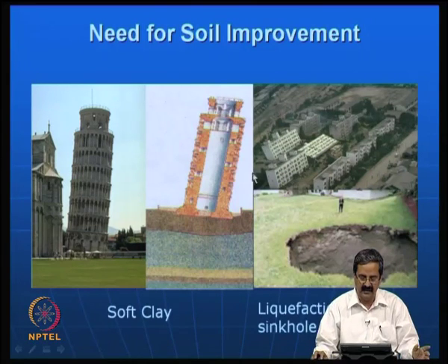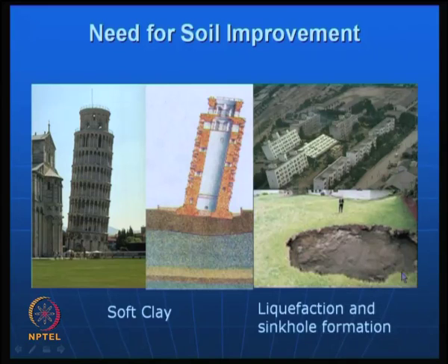This particular case is a liquefaction phenomenon, in which the effective stress becomes zero when the earthquake occurs in the foundation soil. So the foundations just sink in, and you have tilting and total collapse of the buildings. Then this is another type of problem called sinkhole formation. For example, with carbonate soils, because of leaching the soil can get removed and holes form, which is very risky. Fortunately it happens only in a few rare places, like some places in the US and in Germany, where I visited, and it was a very risky situation.